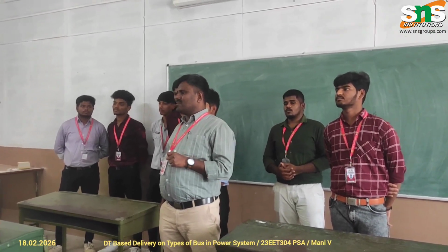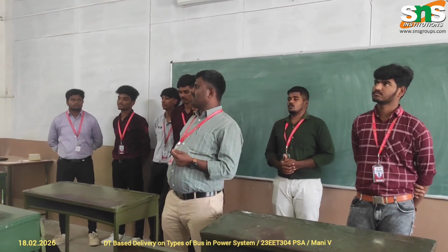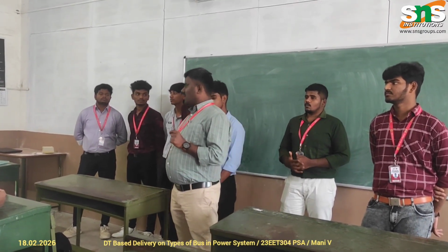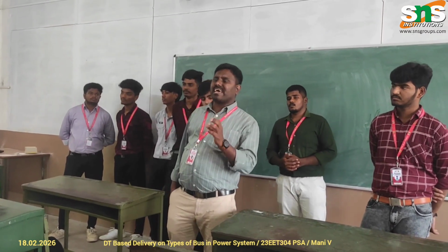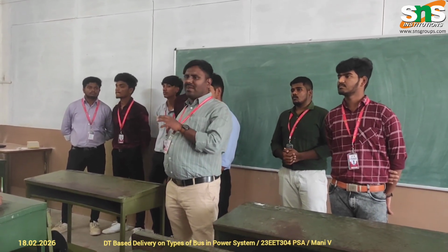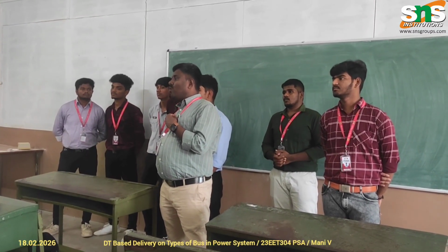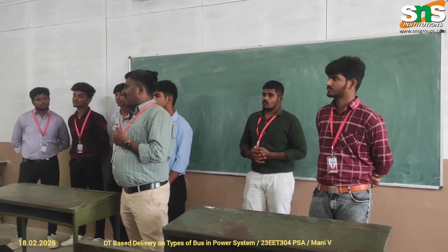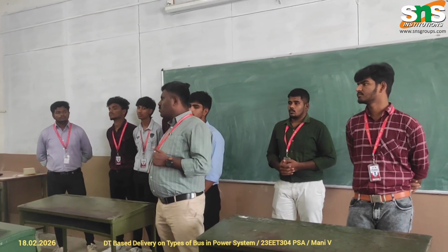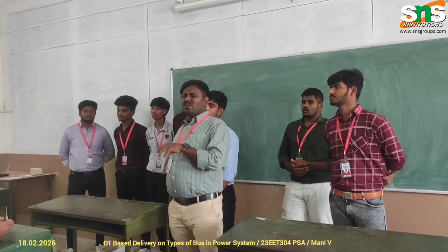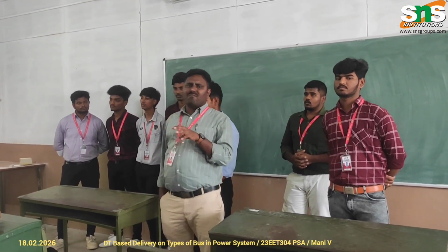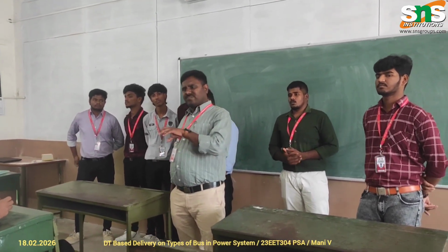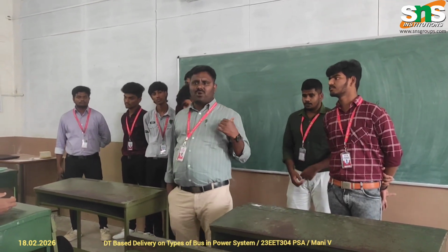So in this reference bus, instead of P and V, instead of real power and voltage, for the slack bus we know the value of the voltage which is supplied to the bus, as well as the phase angle of the voltage. Only these two quantities will be known, and we don't know how much real power and reactive power is generated from the generator and supplied to the load through various buses. So by using the Gauss-Seidel or Newton-Raphson method, we have to determine the real power and reactive power consumed by the various loads as well as in all the buses. So that is called a slack bus.